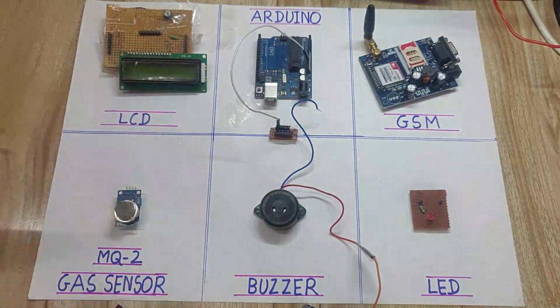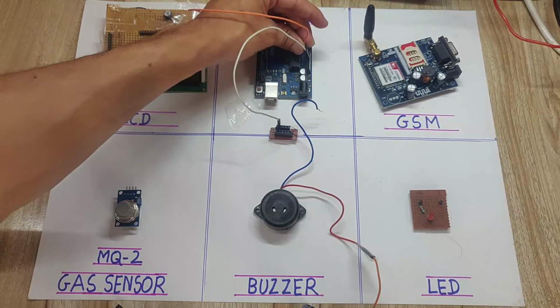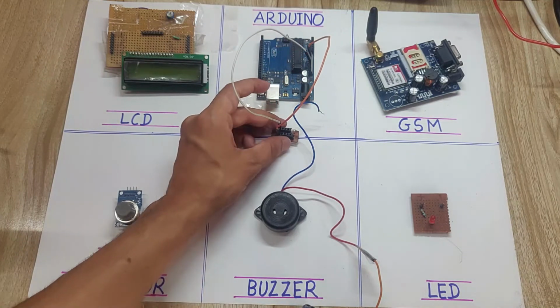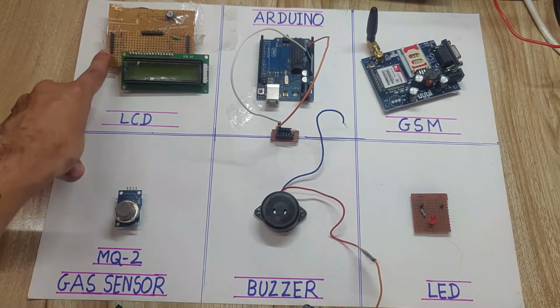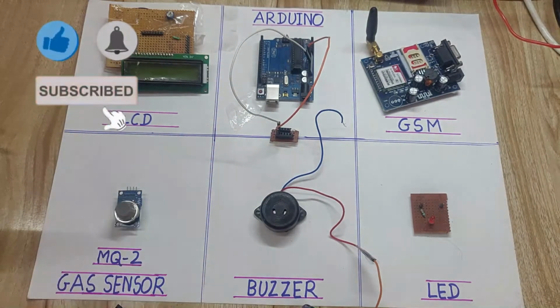And for the second pin, I have to take the common ground. So I will take the common ground from the Arduino again. Okay, now you can see these 2 pins act as a common ground and common VCC. Now the next part is, first you have to connect the LCD module. So connect the VCC point of this LCD to the common VCC point.